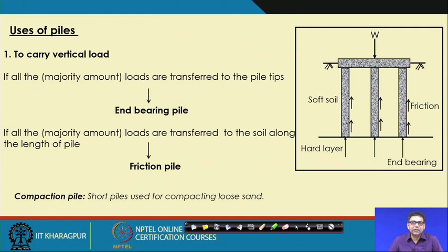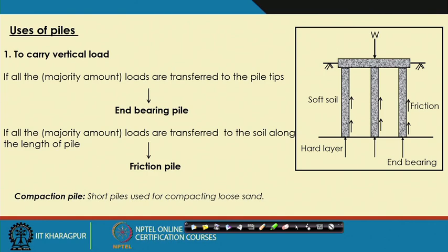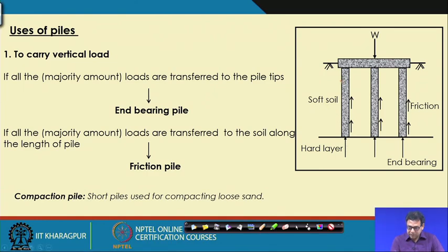In that case, we can go for the pile foundation, where your pile will transfer the load through the soft layer to a hard stratum. Because this is the pile, and if the soil is soft, then it will transfer the load through this soft soil to a hard layer.